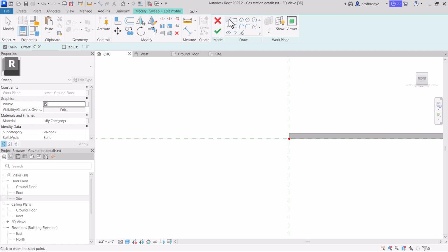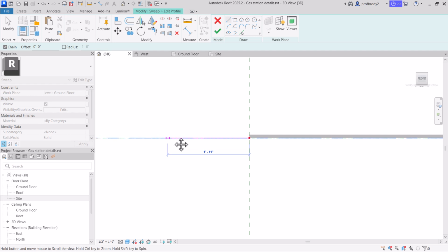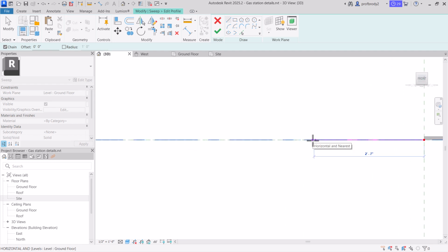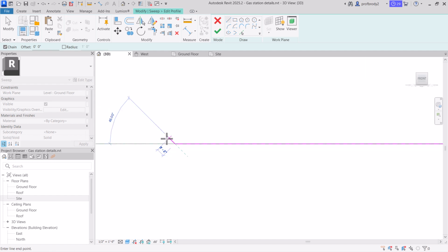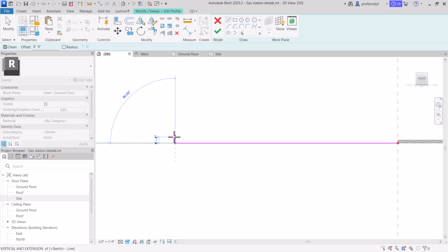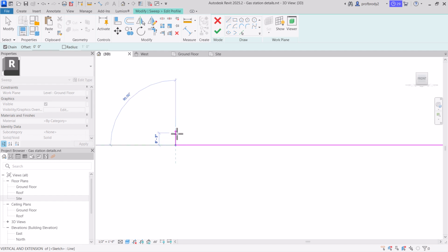And if I had to guess, that looks like a pretty wide sidewalk. So it's about 6 feet, I'd have to guess. So we can go out, we can type in 6 feet. That brings it up. It does look pretty long, but it's pretty skinny. That's fine. Anyway, and then we want to draw the profile of the curb, which has kind of a rounded edge to it. So I'll just draw it up about 3 inches.